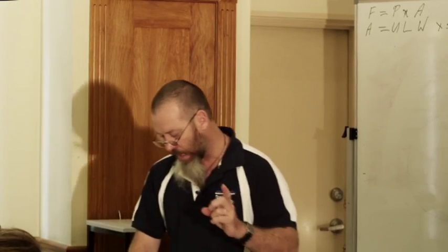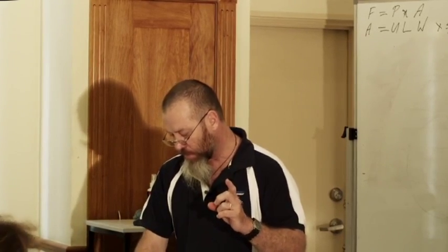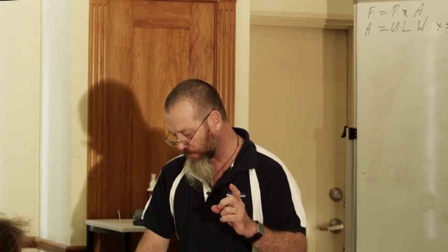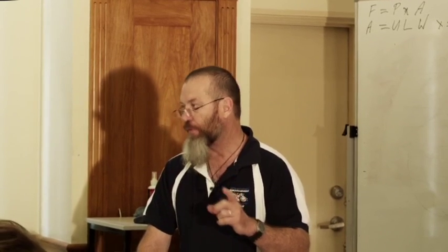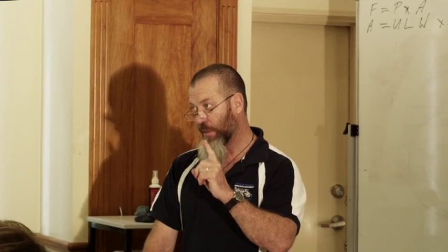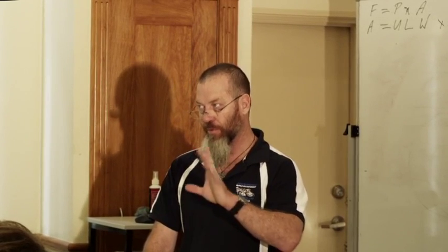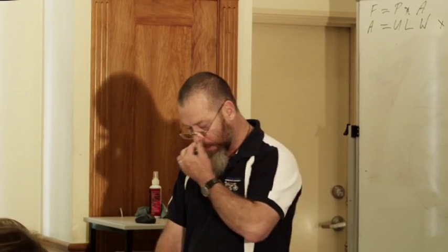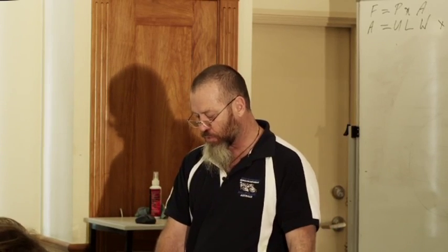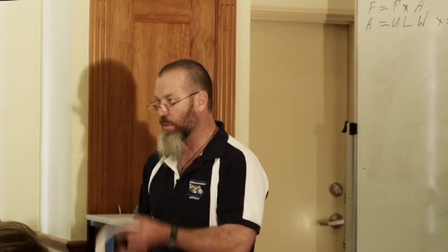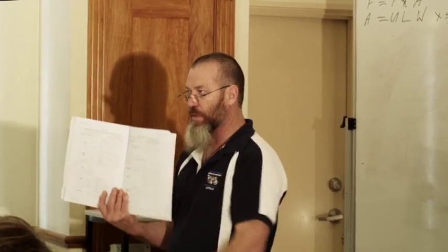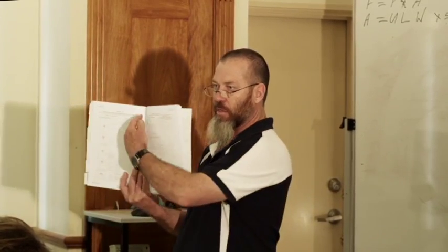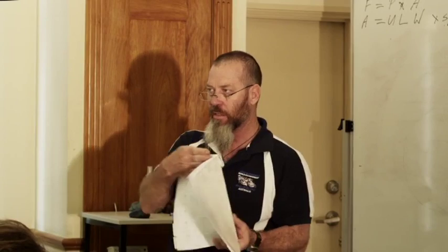Now, by way of example, for a tiled roof, and there's a couple of things here, I'm setting you up for a fall, but it's so you learn. I want you to find a connection for me that will do 0.29 of a kilonewton. It's got to be equal to or greater than 0.29 of a kilonewton. So start at the top in JD5 at type B and see what you come up with.